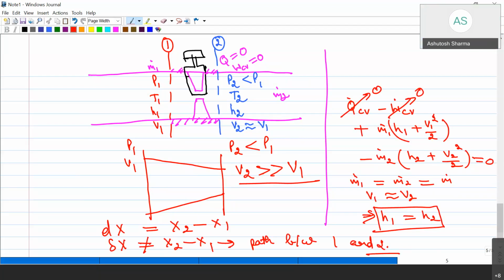But sir, why is it happening? Because we have seen that work and heat, though these are nothing but forms of energy, only come into picture while a process is happening. So work and heat are not defined at any thermodynamic state of the system. At points 1 and 2 these are not defined; rather, these are defined in between the equilibrium states while the process is happening.